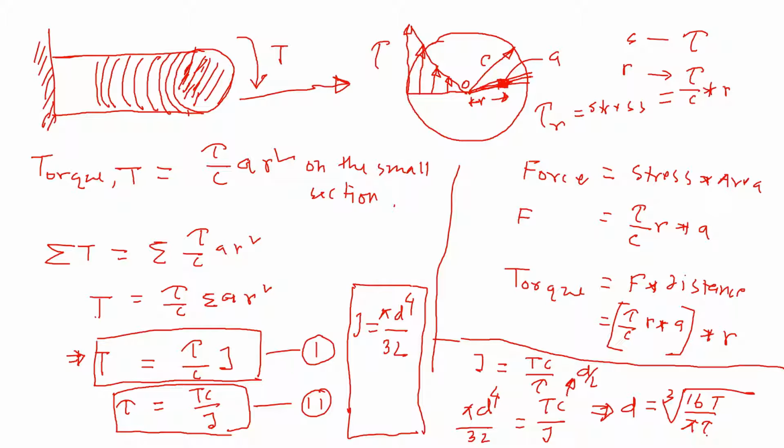allowable shear stress. Now this piece is not J, this will be shear stress, like that. So pi times allowable shear stress. This is a design problem, so we want to find out what the diameter of a shaft would be. So that would be equation number 3.